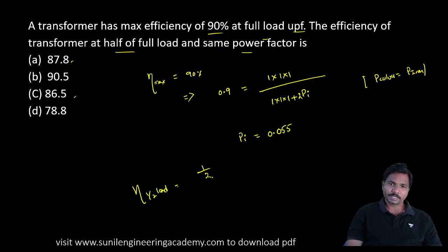Whenever it is half of the load, x is half. So half into 1 into 1, over half into 1 into 1 plus... here 1 is nothing but kVA, and this is nothing but the power factor, guys. Don't confuse. Iron losses are constant at any load. Copper losses at half of the load...